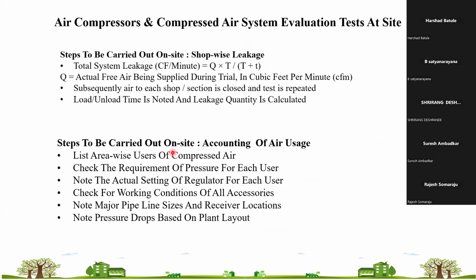But during your free air delivery test, you got to know that your compressor is delivering 80 CFM only, and your consumption of power is around 15 kilowatt only, but your delivery is reduced. So your specific energy consumption goes to 0.1875. From 0.15 to 0.1875, you will have a loss of energy. So 0.0375 kilowatt per CFM. If you are delivering 80 CFM, then 3 kilowatt is wasted.